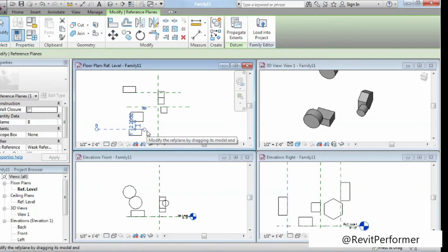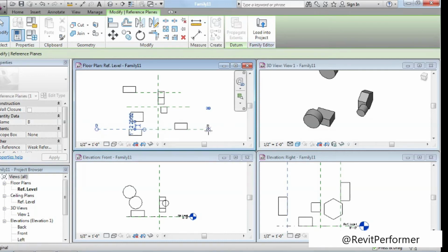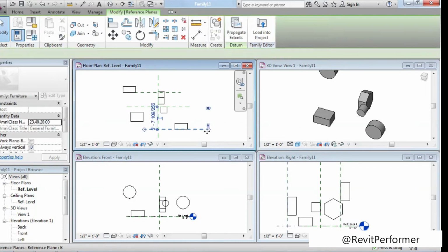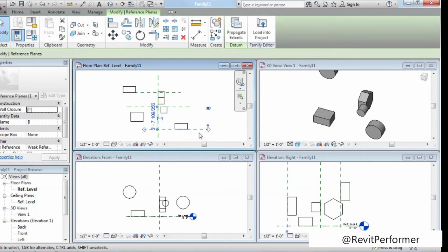Now I'm standing here looking toward this direction, and the extrusion is still going to the left. Okay, so again, just always imagine you're standing at the start point, looking toward the end point, and the extrusion will go to the left. You reverse it again, see how it flips around to the other side. Another way you can look at this is the label tends to be at the second point. It tends to be at the end you're looking at.